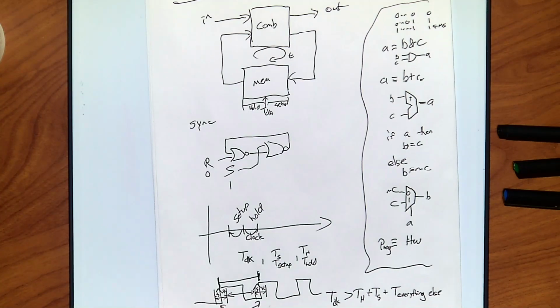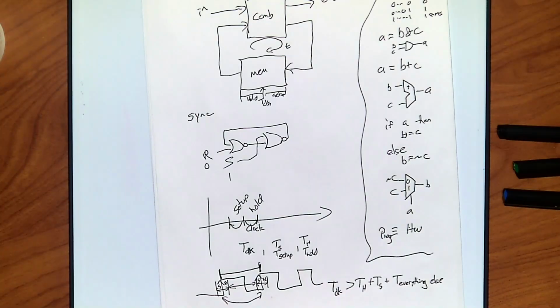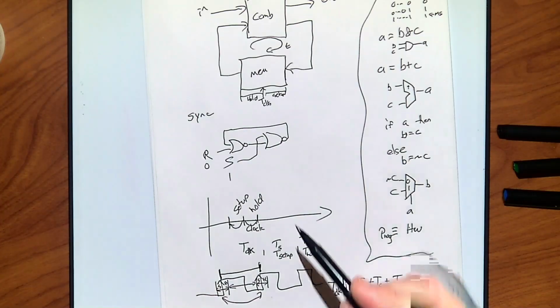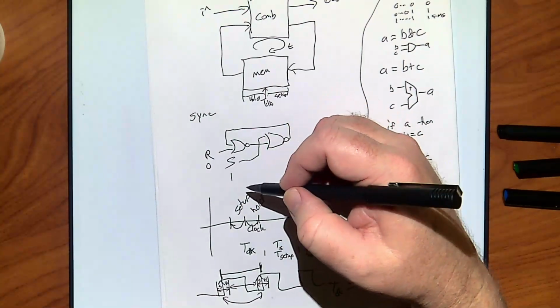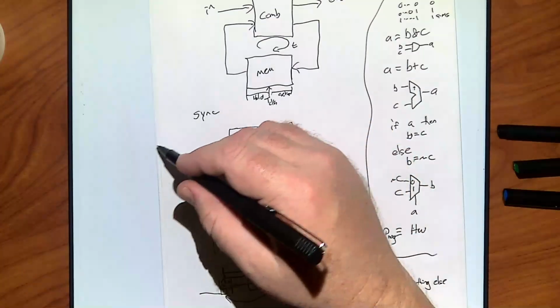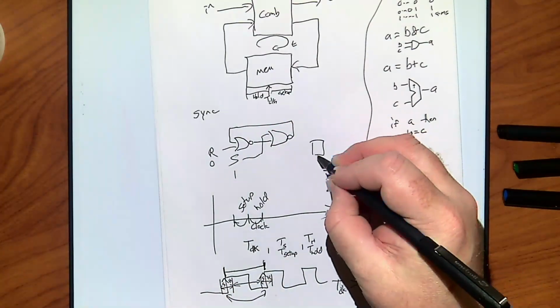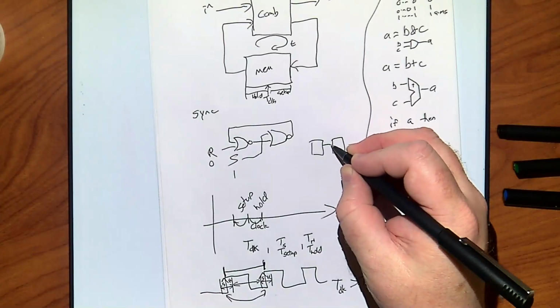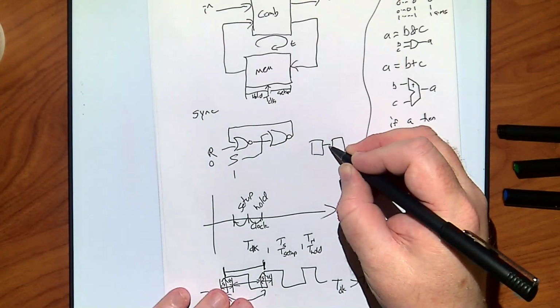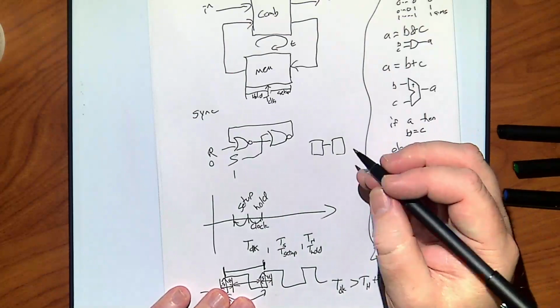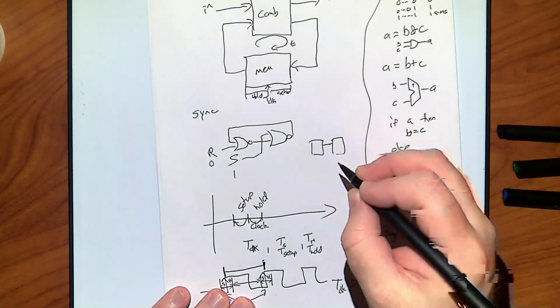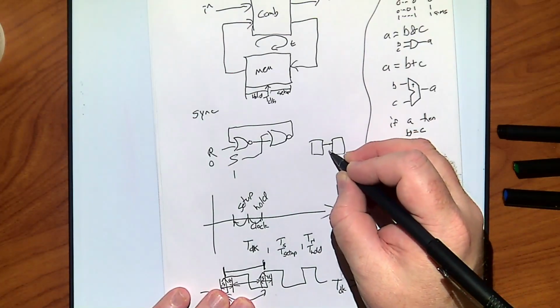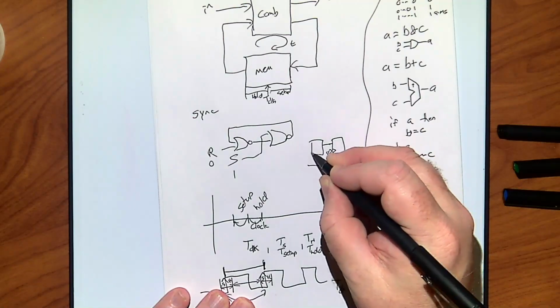Okay. So let's talk then about what we can do with these. Now we have some idea here. Let me add that one extra little provision I said about the T hold. Take a look at my circuit. How long does it take? Usually before this, the simplest design that I can do for some type of flip-flop to get an edge transition is I pass things through and I have an inverted clock.